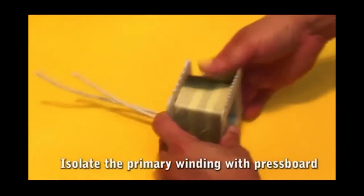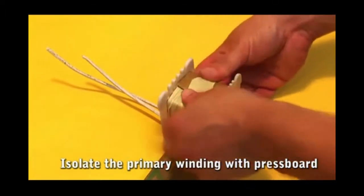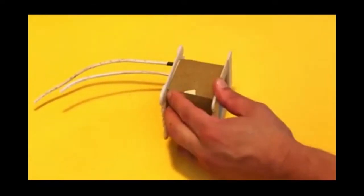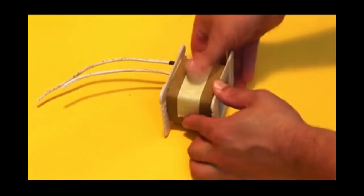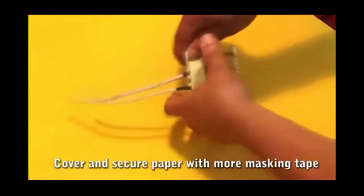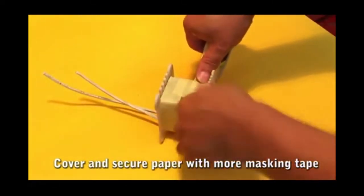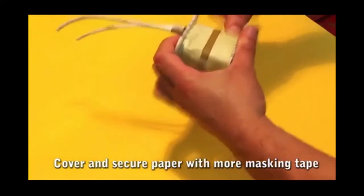The wax paper should cover the entire winding and be secured with masking tape. Then, the paper is covered with more tape. Make sure there are no spaces through which the primary and the secondary winding can touch.